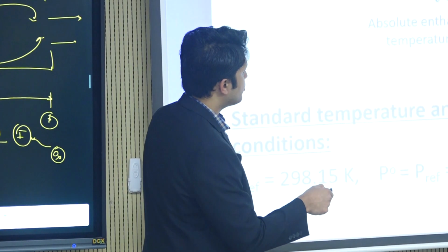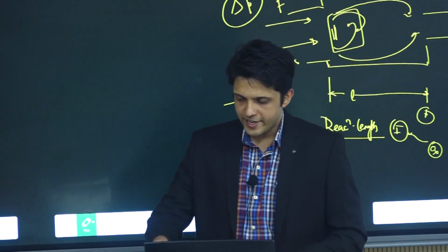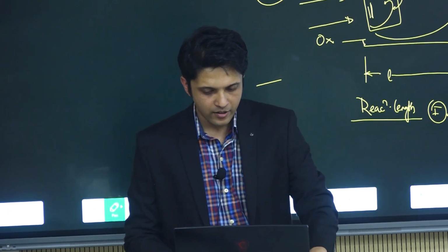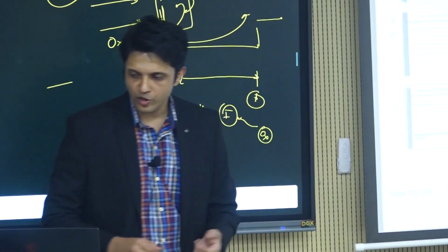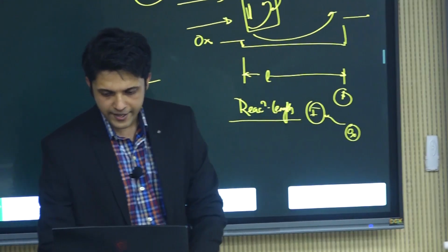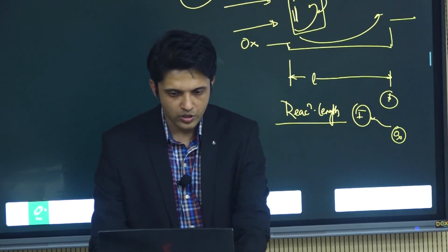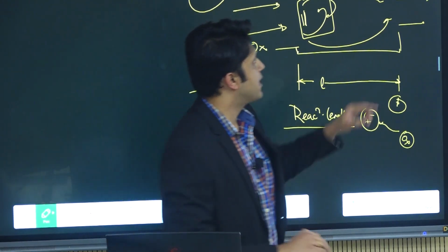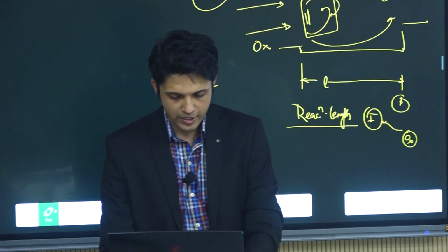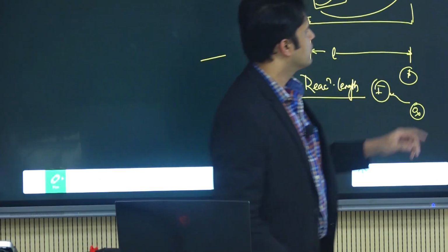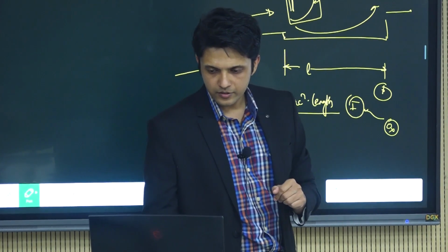These values for the species are available online. There are standard databases that you can look at. I'll just show you quickly. These are the NIST JANAF thermochemical databases that you can use to find the species details, right? If you just Google, you get this kind of table, and you can enter the particular species. For example, let's look at methane, CH4. You get that, and when you click submit.